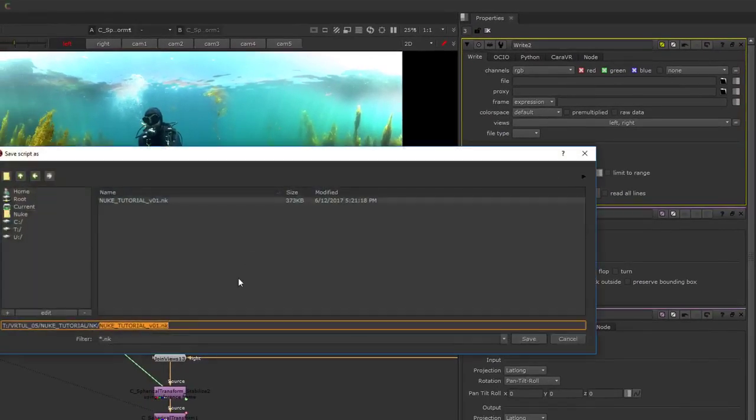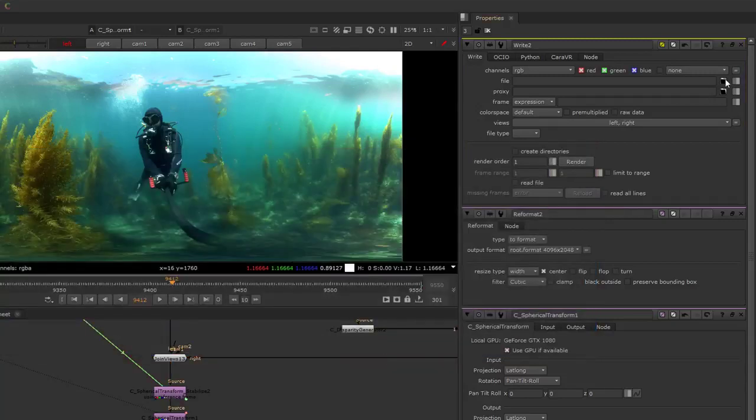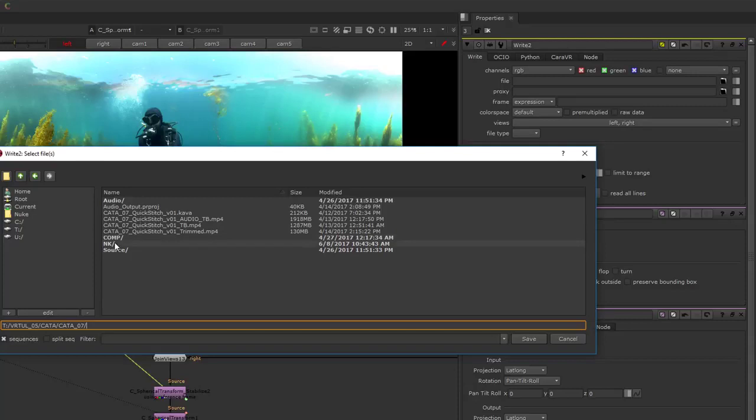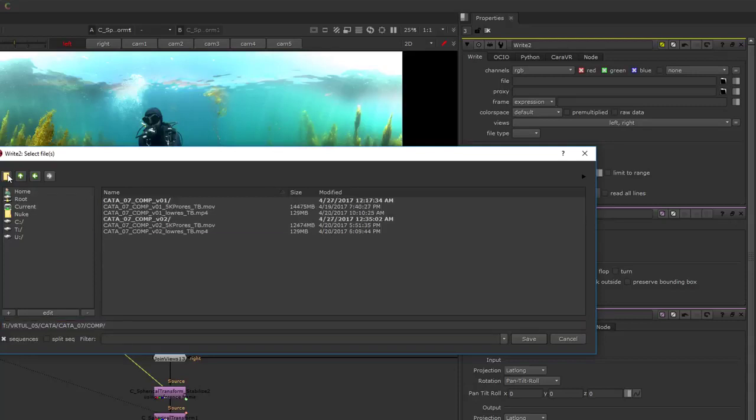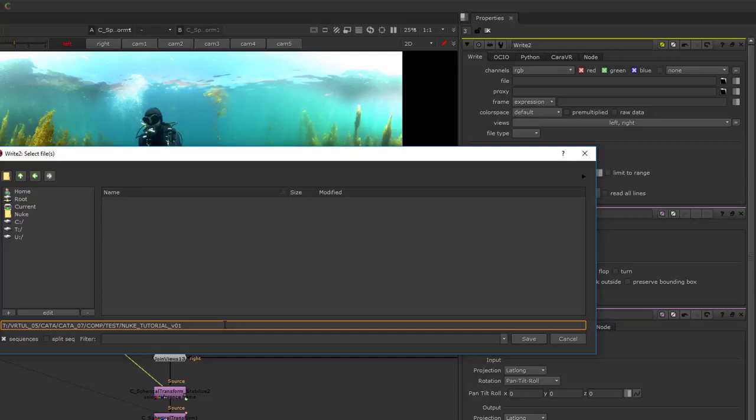And in here I'm going to quickly copy and paste my tutorial name and find a directory where I would like to save this. I'll just go ahead and save this inside comp, inside a new folder that says test, and inside there plug in my name. Then I'm going to underscore %v because I'm rendering out multiple views. I'm rendering out the left and the right eye. You would just skip that part. Dot %05d dot exr because I'm going to render out exrs, and I would like it to have 5 frame padding. That's what this %05d stands for.